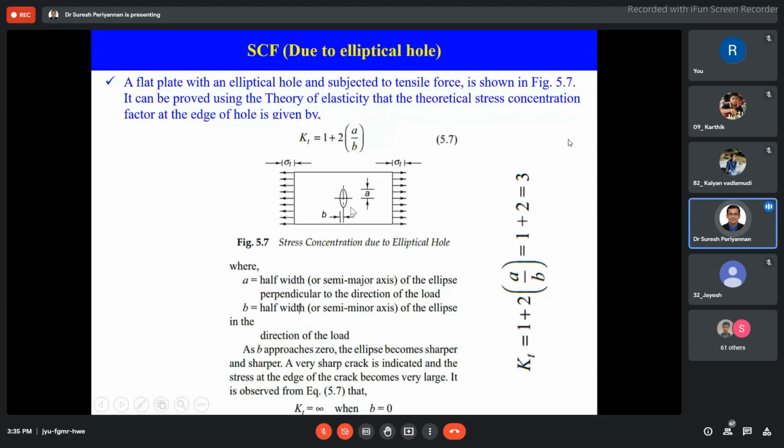So a crack always has more stress concentration. That's what we discussed. We have gone through one video also, which I presented yesterday. The lines looked like pencil lines we had drawn before the experiment. But when the crack is subjected to load, there will be more failure, right? The failures start from the cracks because the stress concentration is more in the cracks. Hence, micro and macro cracks are also important in the design consideration.